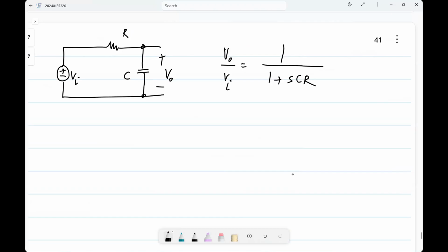Okay. So now where is the noise in this circuit? Resistor. Okay. Would it be convenient to use a voltage source as a current or a current source as the model here? Voltage source. Why? Because we already calculated half the answer, right? So if I have Vn here, what will be V naught by Vn? Obviously the same.